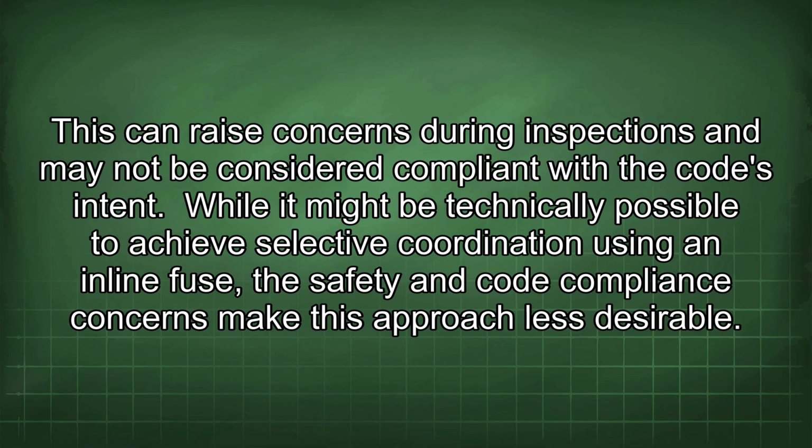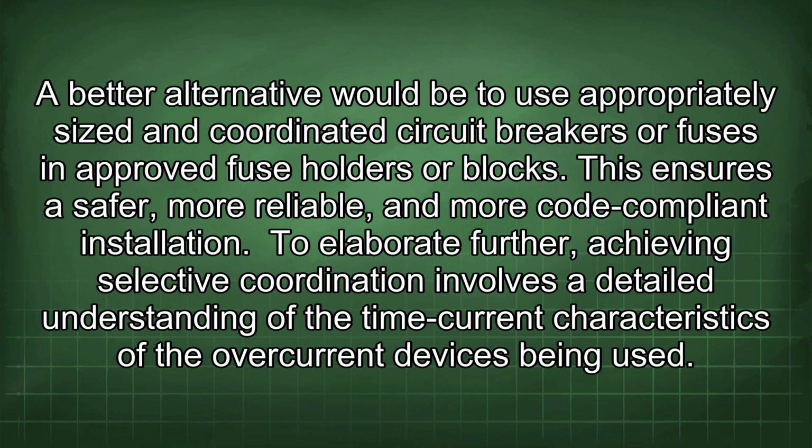While it might be technically possible to achieve selective coordination using an inline fuse, the safety and code compliance concerns make this approach less desirable. A better alternative would be to use appropriately sized and coordinated circuit breakers or fuses in approved fuse holders or blocks. This ensures a safer, more reliable, and more code-compliant installation. To elaborate further,